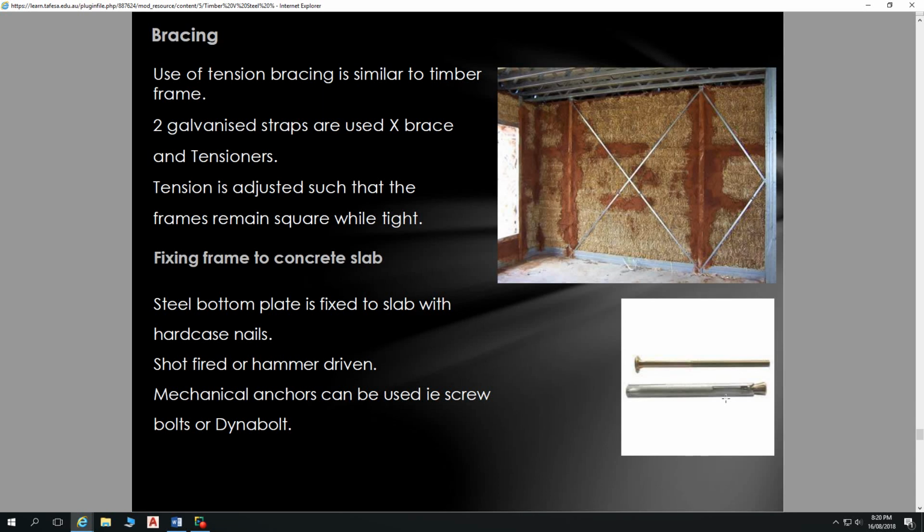There's very little pressure outwards, and so they set into the concrete, and that's how they achieve their tie down. Chemset's really good for that, and also really good for fixing new stuff into old buildings where you've got crumbling mortar and walls that aren't really strong. Has anybody ever drilled into a wall with a hammer drill and seen it disintegrating around it? Chemset anchors are great for that sort of thing, but a little bit more expensive than your blue tips and whatnot.